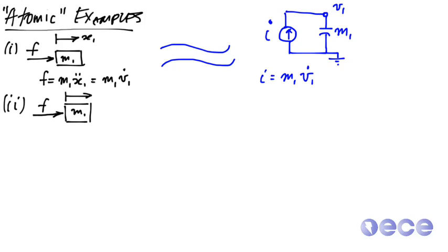Let's look at a second example. Now I have a mass and I'm attaching that mass to a spring. The spring has some constant k1. Let's first talk about what are the ordinary differential equations that map here. F is the sum of all forces, so m1 x1 double dot plus k1 x1. When we push with this force, that's equivalent to the inertial motion in the same direction plus k1 x1.